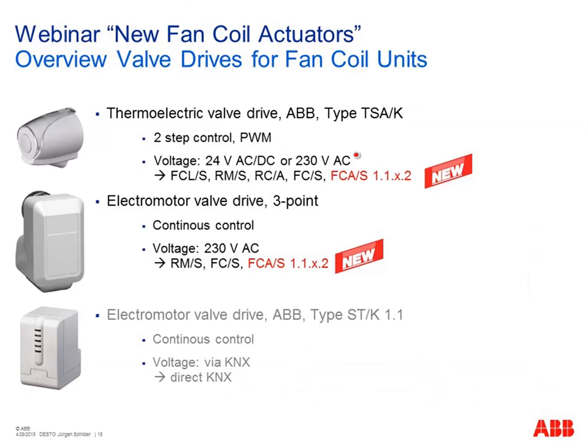Yeah, what kind of valves can we connect to our fan coil actuators? It's very important and depends on the fan coil unit used in your project. Very often and typically we have these thermoelectric valve drives, which are also available from ABB, so in our range available. A very simple, cost efficient and more or less maintenance free device to control the water flow in such a solution. Typically operated via 2-step control or pulse width modulation parameters in the room temperature controller.